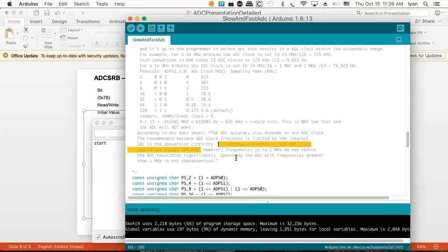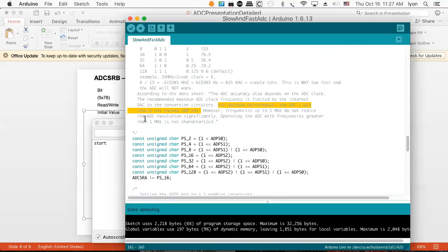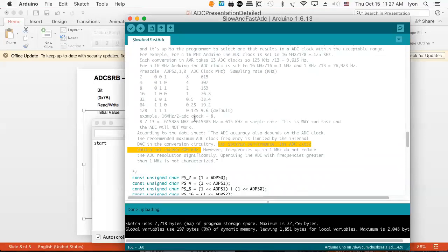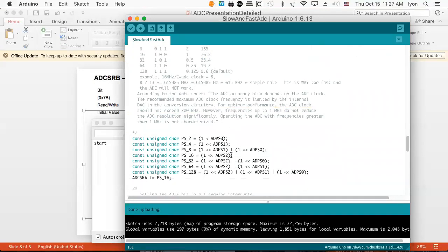So if you're trying to sample from more than one ADC converter and you're splitting the operating rates in this way, you really can't settle for 200 kilohertz. I don't feel you get good results. I've heard it. It sounds terrible. So, you know, going to a megahertz, that's fine. If you go to a megahertz, then you've got 76.8. If you want to split it in 2, you'll have 35 kilohertz. That gives you Nyquist, which will probably bring you up to about 16K, which is fine. 16K of fundamental frequency into a 35K sample rate.